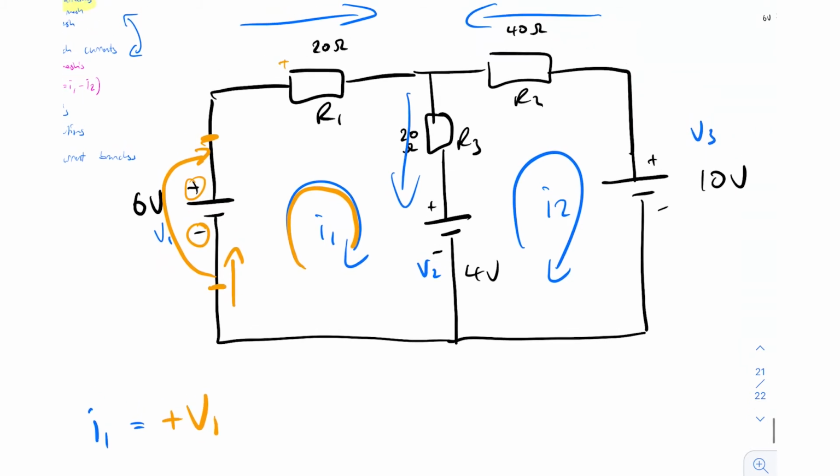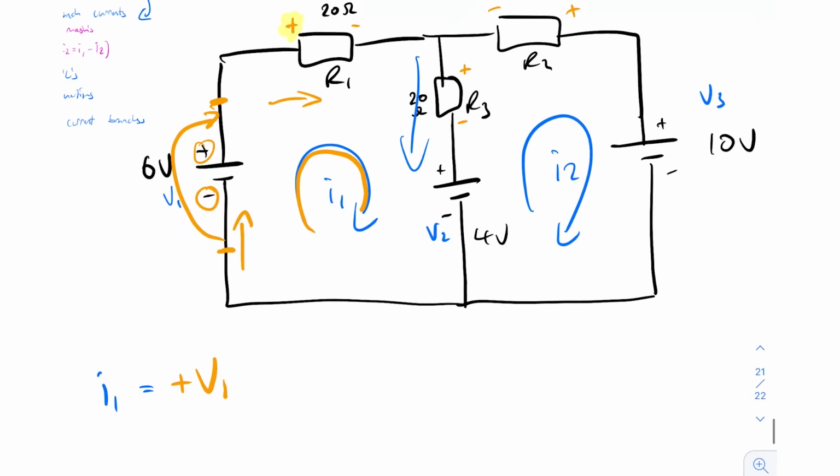And now we've got this resistor. We've said the current's going this way. So this is positive, this is negative. This will be positive, that's negative. This is positive, that's negative. So we've got the mesh now coming this way, and it's meeting R1 at its positive end. So that means you have a voltage drop. So the voltage drop of R1, or you could say I1, really, of I1.